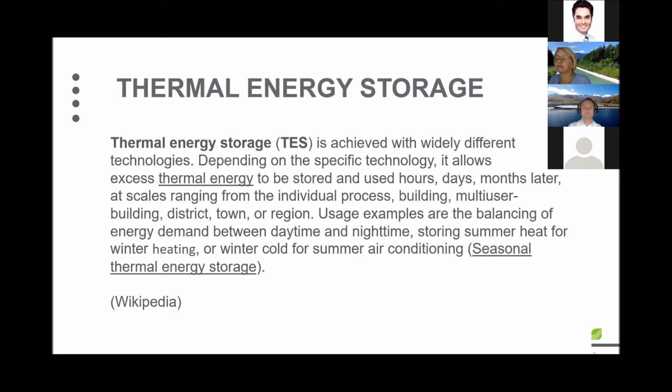This one is taken from Wikipedia, and it shows what thermal energy storage is about. It is achieved with widely different technologies. Depending on the specific technology, it allows excess thermal energy to be stored and used hours, days, months later at scales ranging from the individual process, building, multi-user building, district, town, or even region. Examples are the balancing of energy demand between daytime and nighttime, which we have known for long, or storing summer heat for winter heating or winter cold for summer air conditioning, like seasonal thermal energy storage.